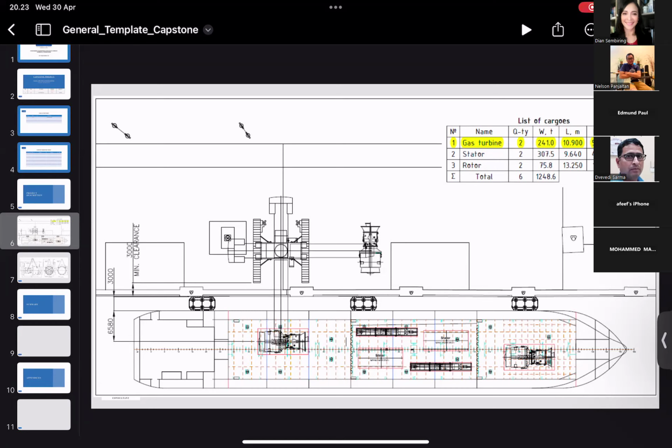No need to be detailed down to the ground bearing pressure, because some crane catalogs don't list the crane weight in detail, so it will be difficult for us to find all the weight and COG data for each piece of equipment of the cranes we use.